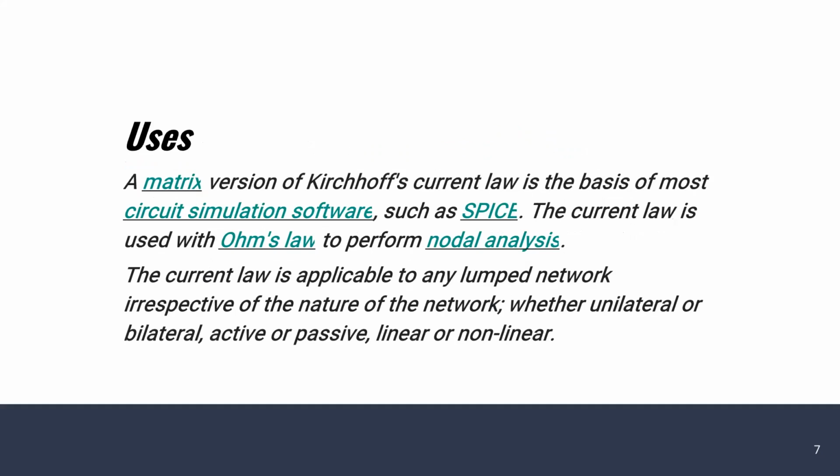Uses: a matrix version of Kirchhoff's current law is the basis of most circuit simulation software such as SPICE. The current law is used with Ohm's law to perform nodal analysis. The current law is applicable to any lumped network irrespective of the nature of the network, whether unilateral or bilateral, active or passive, linear or non-linear.